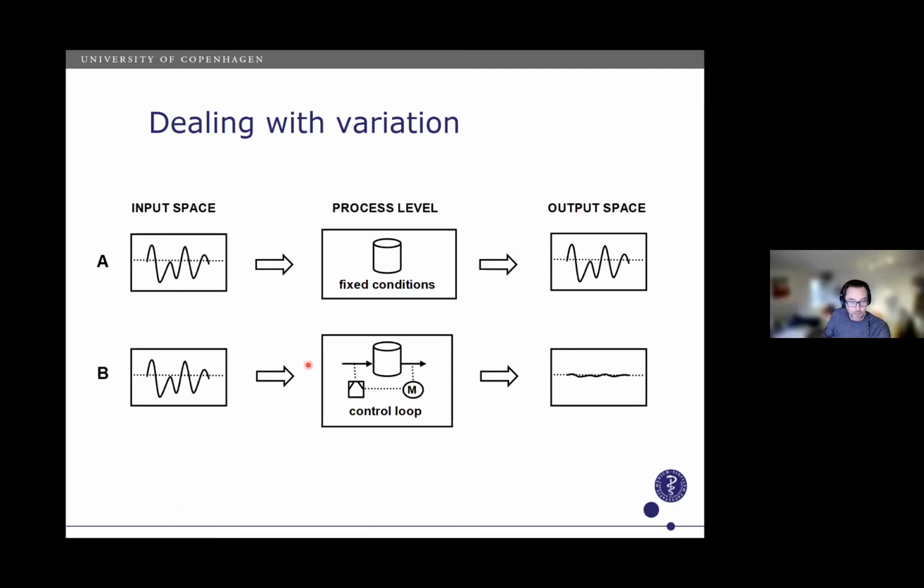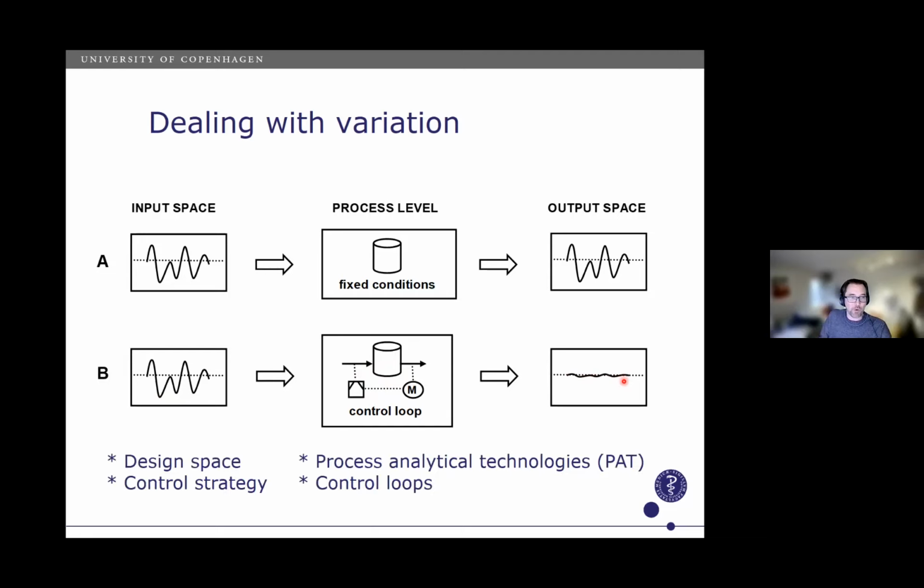If you then, on the other hand, build up process measurements, process understanding, and then control loops in the process, then you can change process properties. So when you are seeing this variation here, you go from this to here. So for example, the moisture content of your excipient is changing from high to very low. Then you can change something in the process so that you always get the desired product quality. So this is simply the purpose and sole purpose of a quality by design approach.